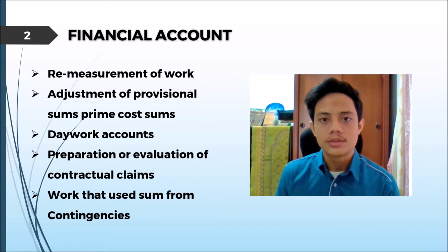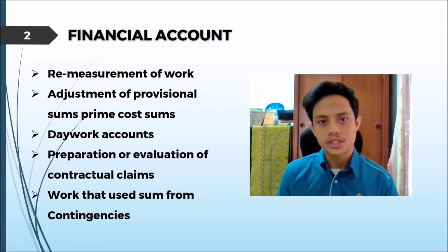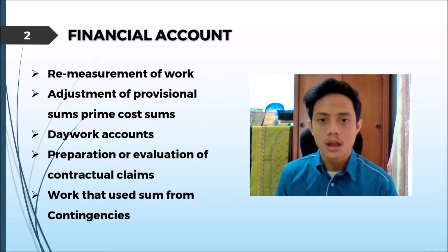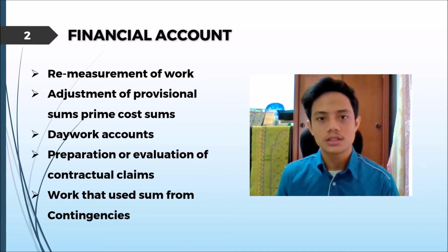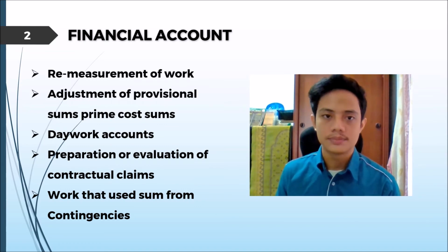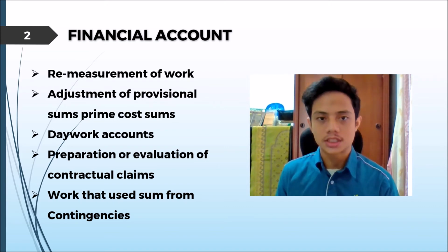For the final task of the post-contract cost control, which is the preparation of the final account, all of the costs of the construction need to be clarified and settled. Any remeasurement of work needed is to be done, such as for the provisional items or quantities.